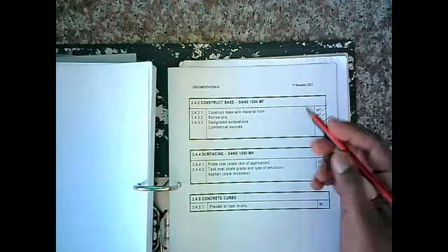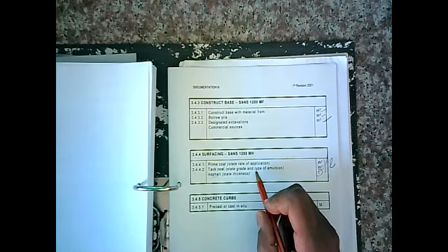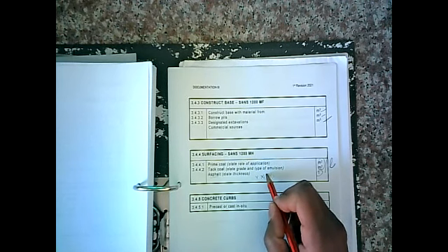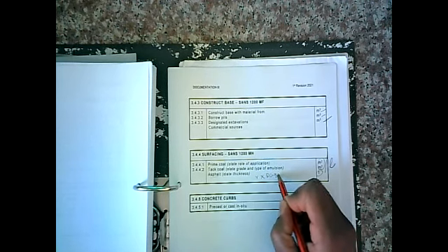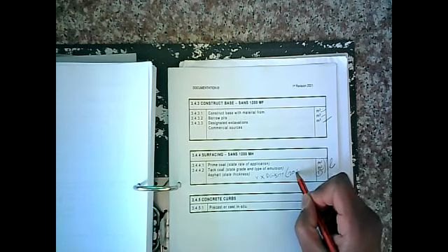All right, prime coat, tack coat, we're going to be looking at area or volume, meters. Right, we know by now what these two are. Asphalt, right, it's going to be reduced to tons, but at the same time, if we have volume, we still need to apply it to the density of asphalt. And what is the density of asphalt? 2080. Okay, so here's a new number for you to commit to memory.